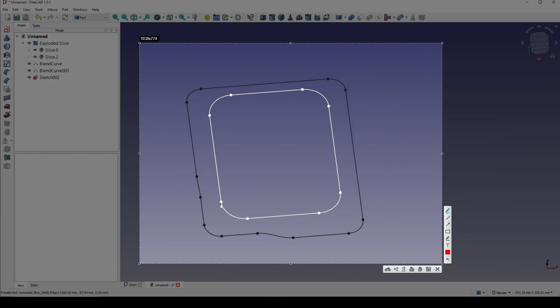All right. So you can see in here, I have this arc and this arc have the same height. So I can use the rule surface to fill in between. Using the rule surface. And in here I have one point and I have this line. But in order to fill in between, I need to split this edge, this one, so that I will have a short edge over here. And then I will use the rule surface again to fill in between.